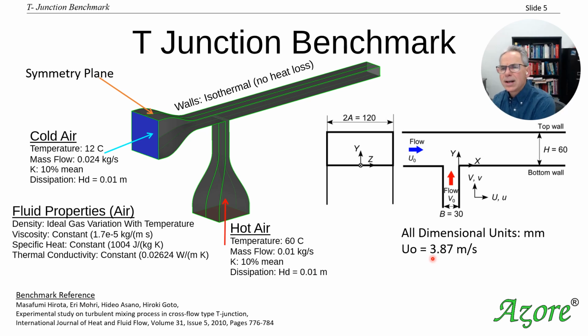And so now we need to pick some coordinate systems, and those are shown over here. Those coordinate systems we're going to use when we look at the experimental data, about where we are and where this data is taken. For the coordinate system from top to bottom in this horizontal section of the duct, we're going to choose our y coordinate to start right at the very bottom of the duct right here.